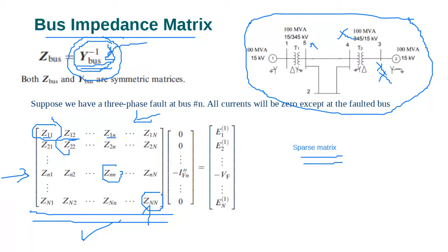What does it mean, the Thevenin impedance? How will Z12 be represented in the diagram? No, Z12 will not be represented in the direct diagram. That's the question here. You do not represent Z12. Z12 has another meaning than what you see in this diagram here. It is the transfer impedance. So you cannot draw this as an impedance, but this is the Thevenin impedance.